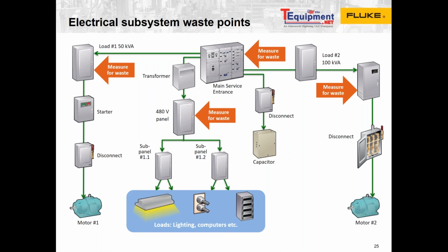And that's getting down to, I would say there's probably 3 or 4 different levels of energy savings hunting. So level 1 is just making sure that your building envelope is good, and your human behavior is good. So please shut the lights off, or install automatic sensors for the lighting, or please shut the window or the door. We really don't need to leave it open. You're letting the heat out or letting the AC out, whatever. And then the second level would be, all right, now let's take a look at which machine is using the most energy. And then the third level is looking at your operations.